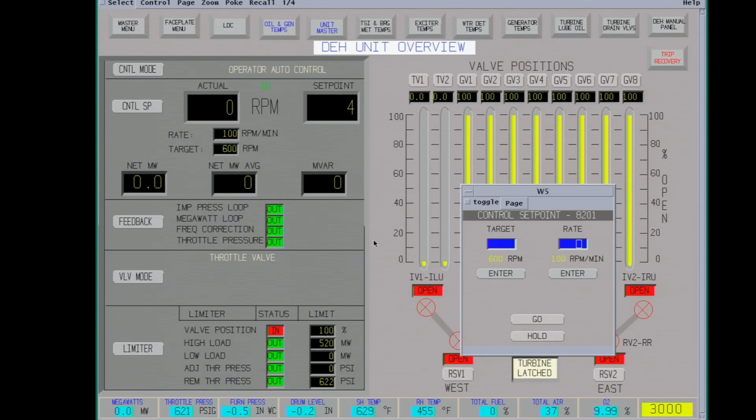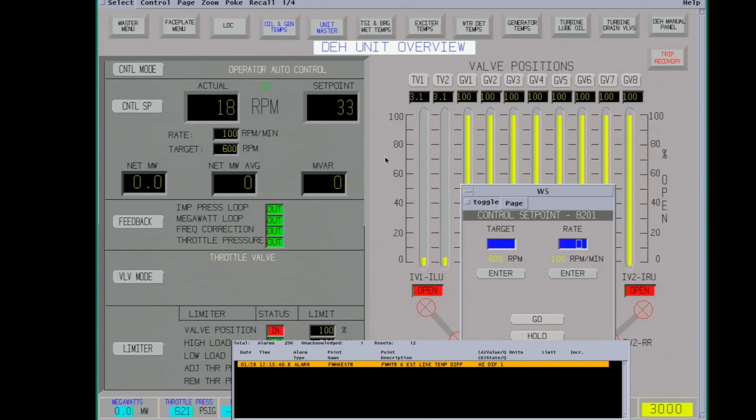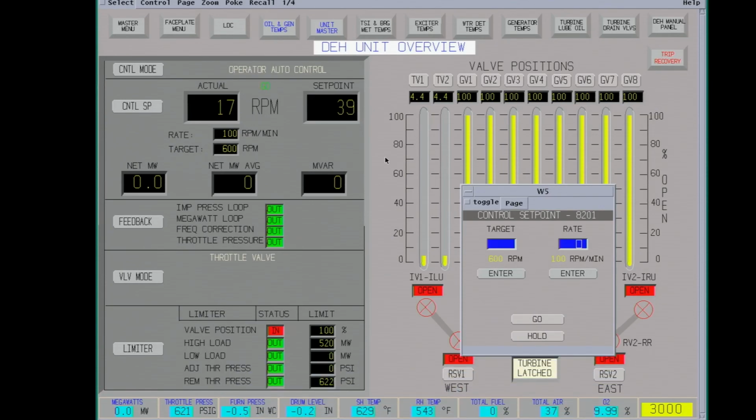One thing you have to do is reset the 86 lockouts, electrical lockouts for the breaker. They trip when you trip the turbine. Attention all plant personnel, rolling the turbine generator to 600 for rub check. Rolling turbine generator to 600 for rub check. About every 2 weeks, do a valve test just to make sure the valves are free to move.